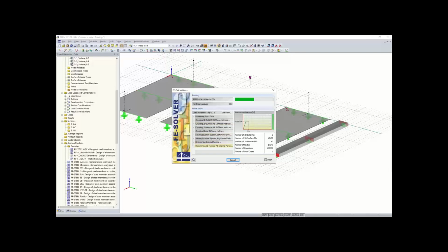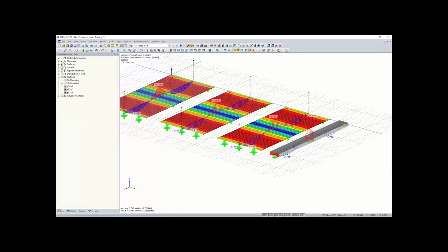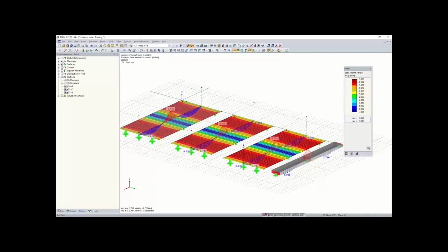Basically, this is because the methods used in school, like I said, assume an infinite shear stiffness, when in reality there are some shear deformations for bending. So just keep this in mind when comparing hand calculations of deformations with RFEM. So now back to the PowerPoint, we can go over some plate theory. So now I'll take this back to the PowerPoint.